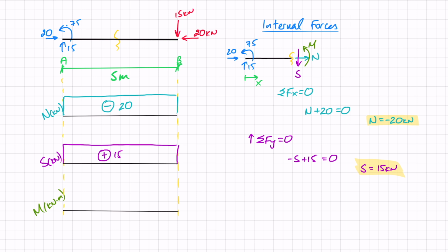And the last thing that I'm going to do is sum of moments. I do this at the cut. And the reason I do this at the cut is because it'll eliminate the shear force I've just calculated. So if I've made a mistake in that shear force, I'm not going to be carrying it with me. So let's see what we've got at the cut.